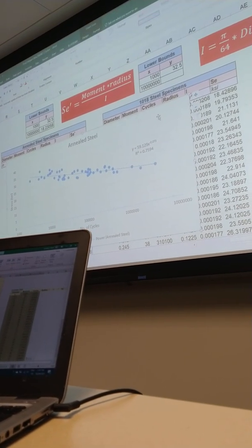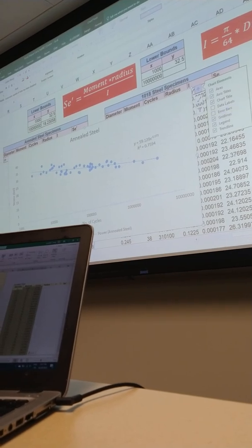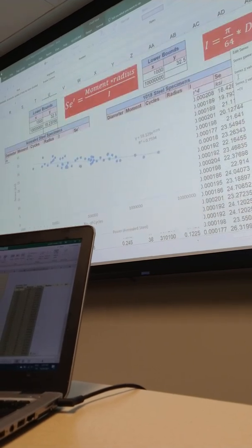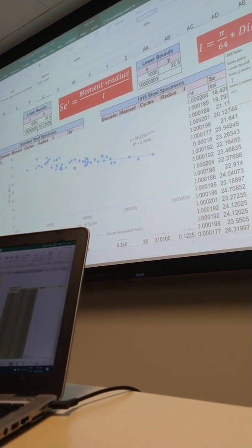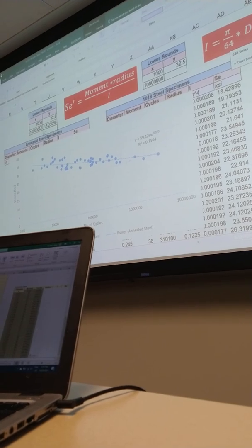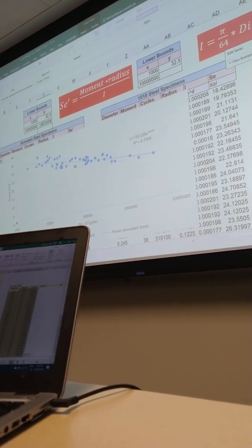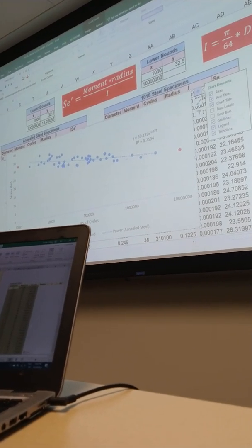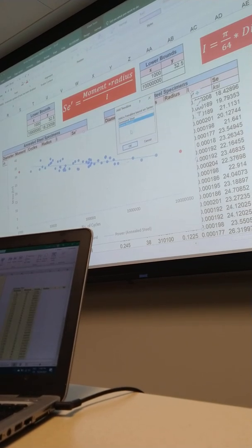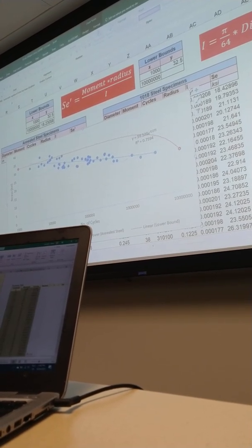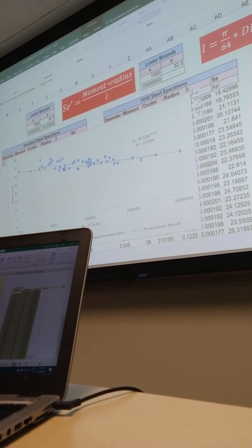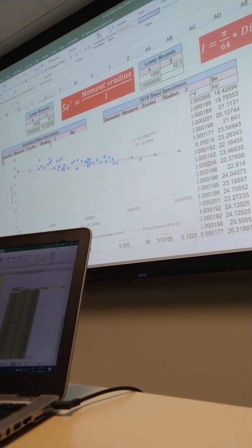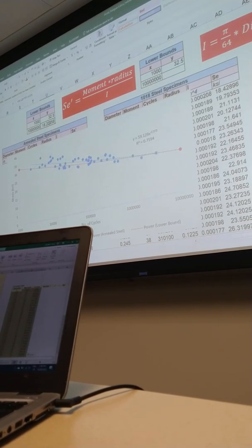Okay. We're going to go ahead and add that line. We're going to add data, add, and call it our lower bound. Here's our x's, here's our y's. Okay. And then give it a trend line. Make sure the trend line is a power line. There we go. That's how you create that. Now, this looks a little funky. Why does it look weird?